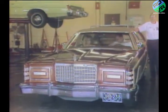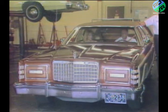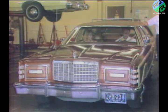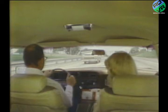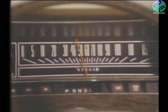Here's how to road test for NVH problems related to wheels and tires. Operate the vehicle in the speed range where the vibration occurs. And then accelerate to 10 miles an hour above this speed.